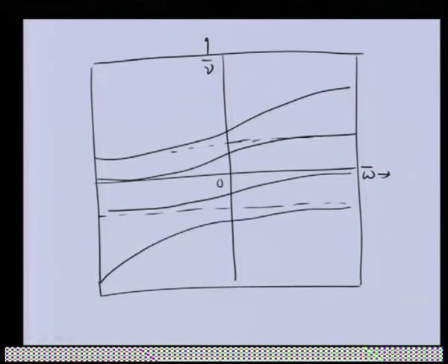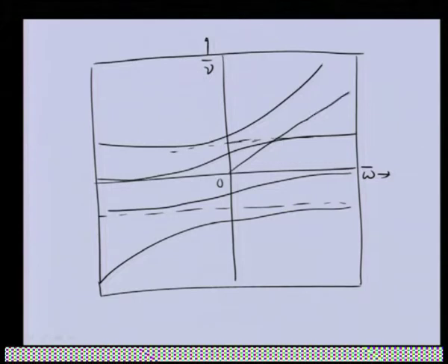so these are the 4 lines, 1, 2, 3, 4 lines which will be there, and if we draw nu is equal to omega line, this line will be something like this. This is a nu. So, we are interested in the spin speed, critical speed. So, intersections of this give a critical speed, one of the critical speeds, and the upper curves belong to the forward whirl. So, this is one of the forward whirl critical speeds. There is no intersection with the second curve.